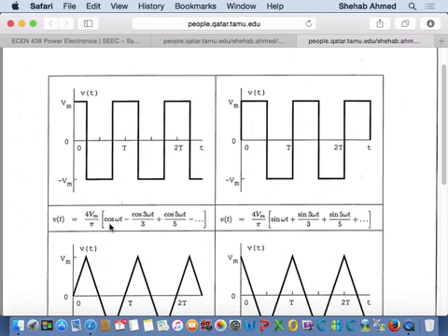And then what's the RMS value of that? What's the RMS value of the fundamental component? The RMS value of the fundamental, this is a Fourier series, right? The Fourier series takes your waveform and chops it up into its components. The fundamental component is the first harmonic. The equation for the first harmonic is 4v maximum over pi cosine omega t. What is its RMS value? 4v maximum over pi over square root of 2, right? So that's the RMS value of the first component.